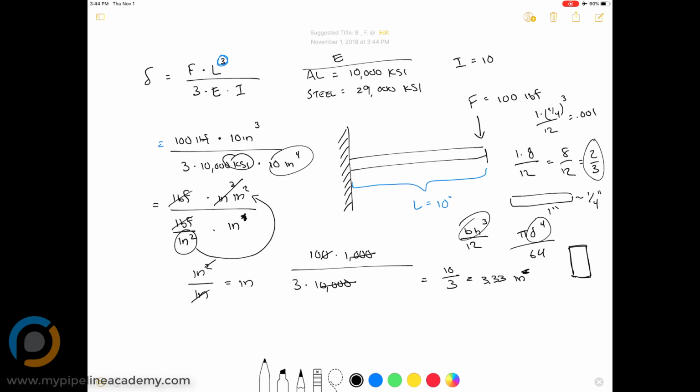That's much more complicated. And honestly, it's not something that's used very often, because if something is plastically deforming, we're probably not very concerned with how much it's deflecting at that point, because it's plastically deforming, and that is usually a bad thing. And so we just want to stop there and say, okay, back up. We need to change something because we don't want this to plastically deform. So 3.33 inches, you know, that's probably beyond its plastic deformation range, which means that answer isn't even really valid.